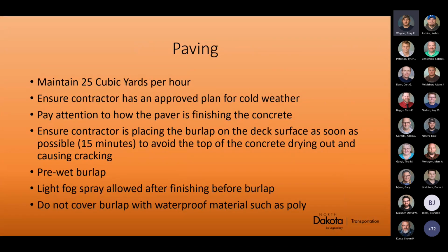A few things to note. Spec book says maintain 25 cubic yards per hour. You just want to make sure you're staying ahead so you don't end up with your concrete starting to dry out.